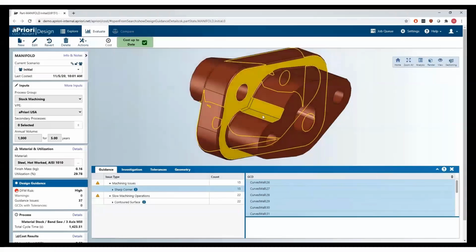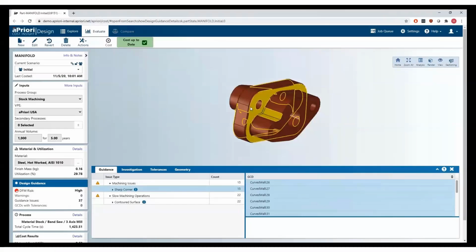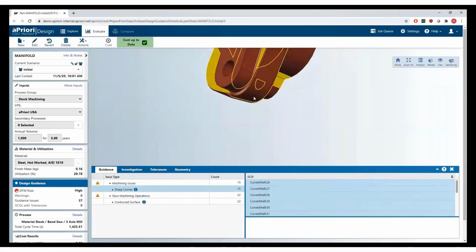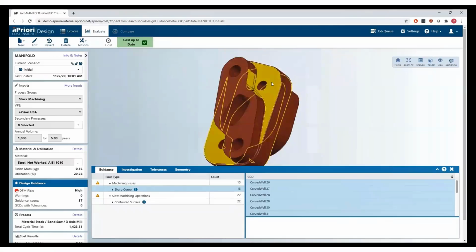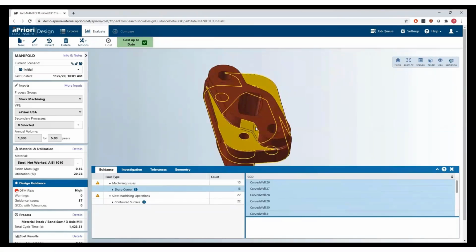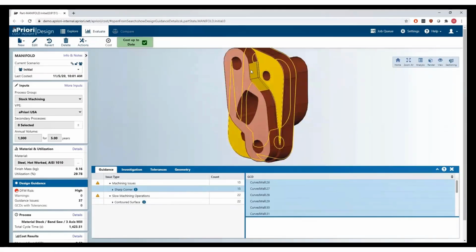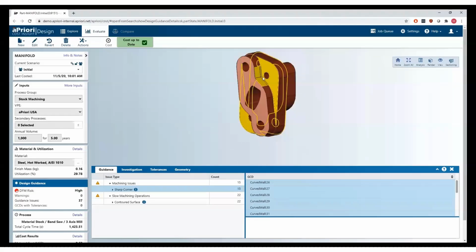Oh, okay. This is pretty obvious to me. It looks like it's in a few of these corners that I modeled. I really just made a simple mistake and forgot to add my rounds in these corners. So this will be an easy change for me. Really has no impact on my overall design. I just really need to make sure that there's clearance for the mounting bolts to go through and clear these areas. So I should be able to add a round there, no problem.